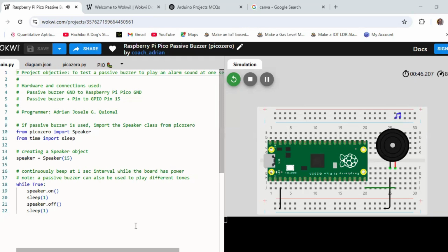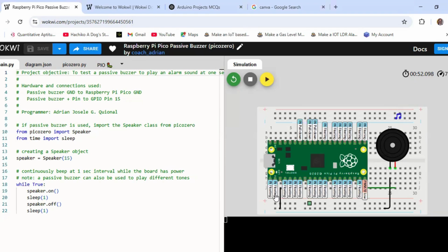We can do it on the Thonny IDE. We can just copy and paste it into Thonny IDE. These pin connections are very simple, very basic. The only new thing is the piezo speaker. These are the 2 libraries we have shown here, and the speaker output pin is 15. Sleep time is nothing but the delay time, what we call it here. So this is the circuit, and it is in MicroPython code.